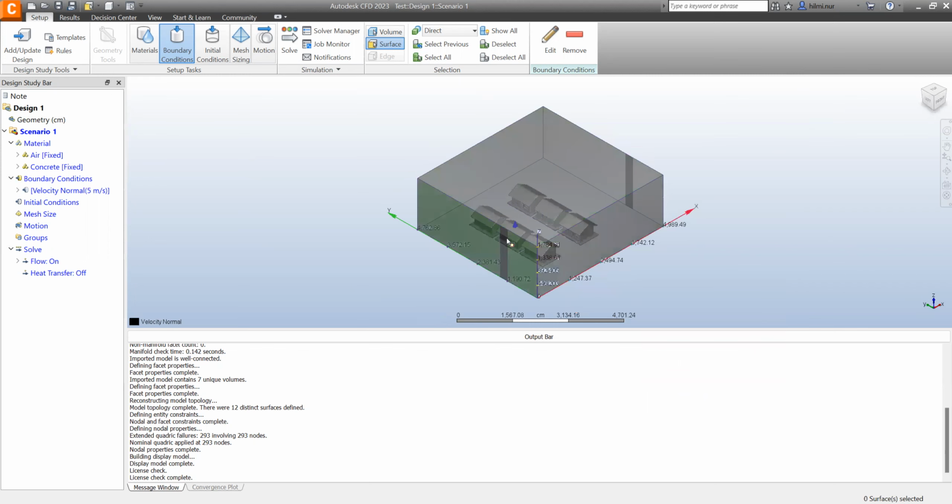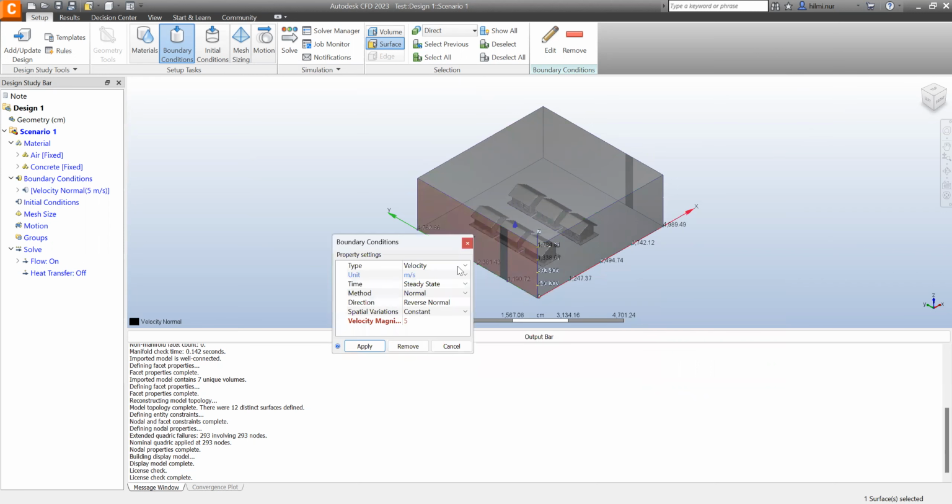And then for the exit areas, edit, then change into pressure, but in 0 PA, the unit also PA, and everything is static. Do you know why it's put as pressure? Unlike the other type, the second one, the exit will be pressure because there will be a pressure from inside from this area to this area. That's why this area will experience a pressure. That's why we divide it as pressure. That's it. Okay.